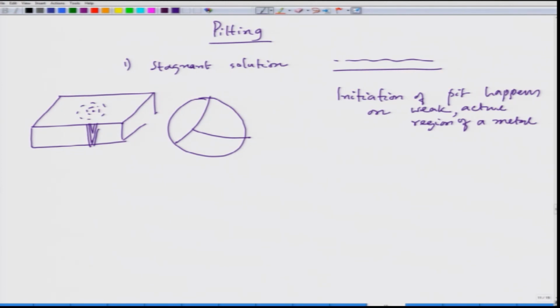So, the mechanism of pitting and mechanism of crevice corrosion are nearly similar, but we are not going to discuss all those mechanisms, I am just saying what the form is. So, this is the kind of form. For example, if we have a plate like this, on these plates you have those small dots, and these dots are nothing but pits, and around those dots you will find a little bit of red rust in case of iron, and many a times it punches the plate.